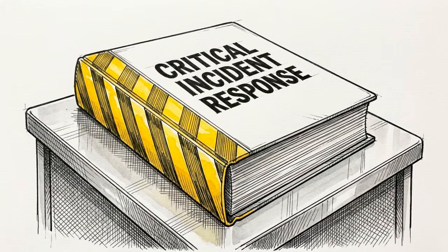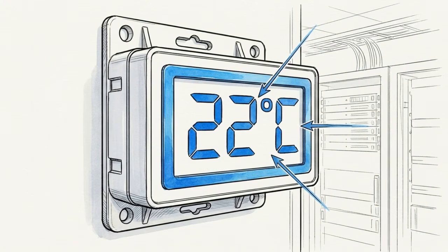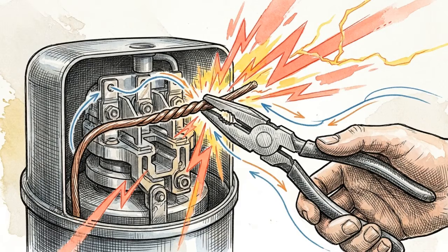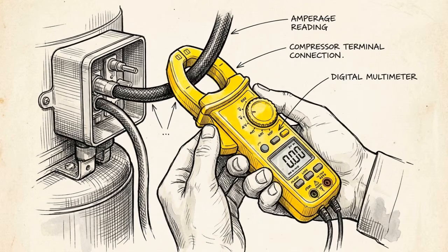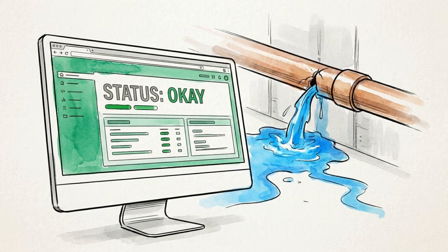When these edge case failures eventually occur outside of a controlled test, facility operators must follow a rigid troubleshooting doctrine. The prime directive is absolute: stabilize the room temperature first. Technicians must never defeat or bypass physical safeties just to force a compromised compressor to run. Operators must validate actual physical sensor states using handheld meters at the equipment. Relying solely on what a centralized BMS graphical interface displays can mask localized mechanical faults.